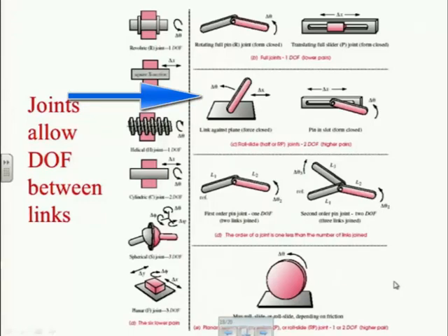So it has 2 degrees of freedom potential between this stick and the table when I put them in contact in that fashion. So we call that a 2 degree of freedom joint, but it gets the name half joint because the 2 ends up in the denominator. So it's referred to as a half joint because it has the effect of half as much as the 1 degree of freedom joint, as you'll see.